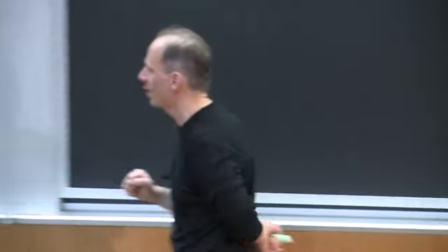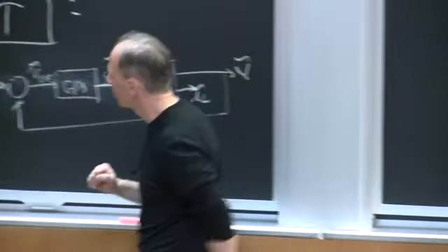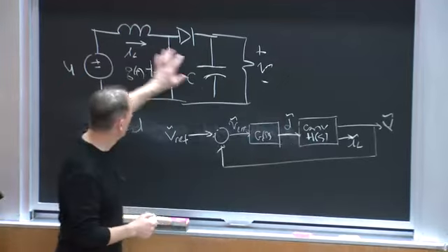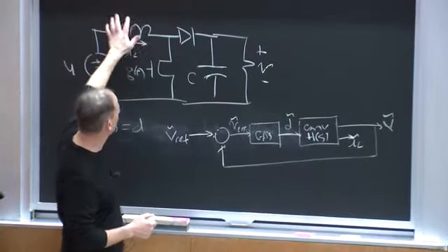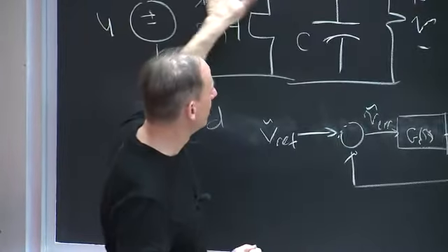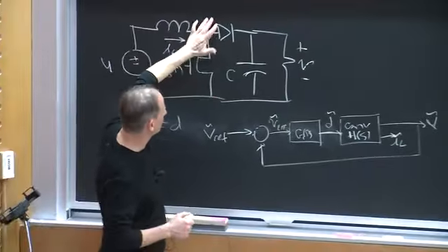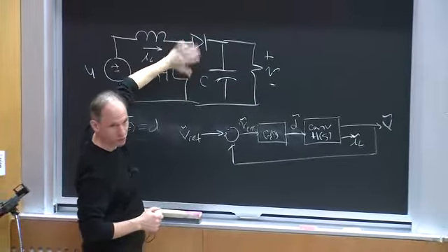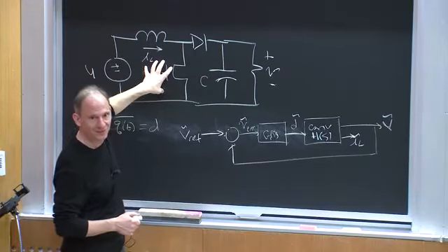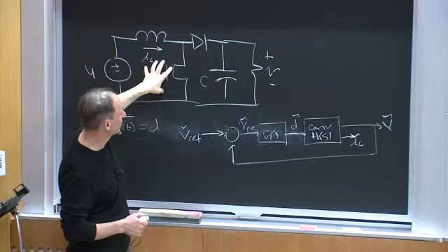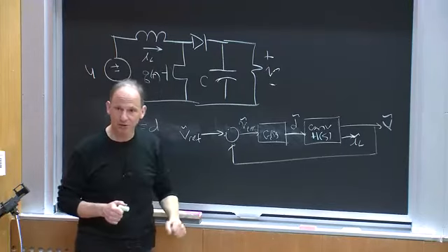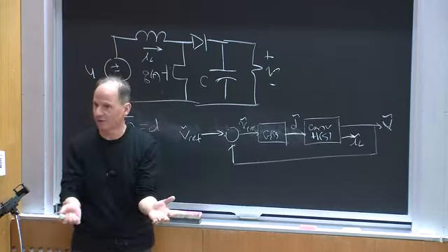And in this case, why is that nonlinearity there? The nonlinearity is there because what we're seeing is second order responses, some kind of oscillations between the inductor and the capacitor, damped by the load resistor. And those oscillations are mediated through the switching or the modulation of the switches, which varies with time. And more to the point, the steady state value of that varies with DC input to output voltage, and hence the dynamics vary.